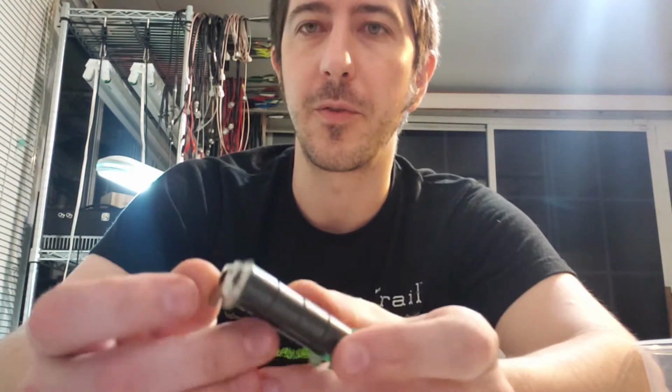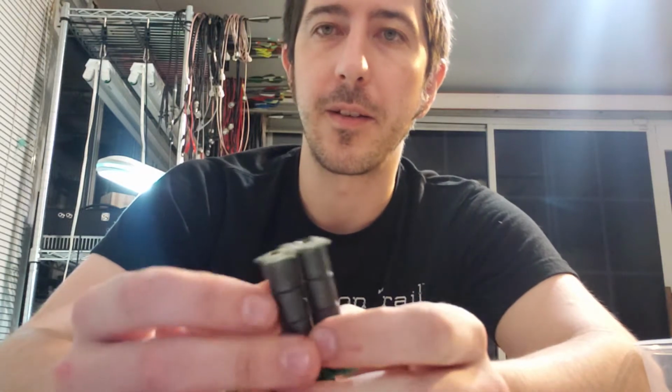The transistor is pretty much always going to have one winding. That's this brass tube, which goes through and connects on the other side. If this is on the output of the transistor, that's your primary winding. These brass tubes going through here are your one-turn primary winding. Then there's going to be a piece of wire wrapped through those tubes, and that's your secondary winding. Typically, there's going to be more than one turn, probably 2, 3, and occasionally 4.